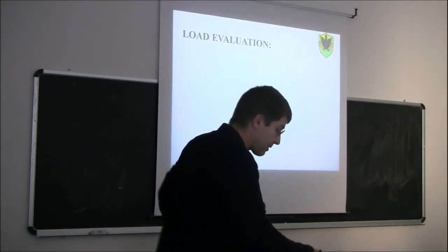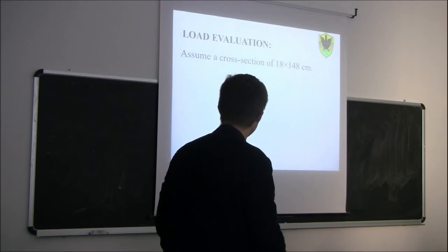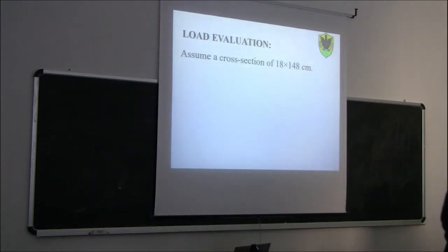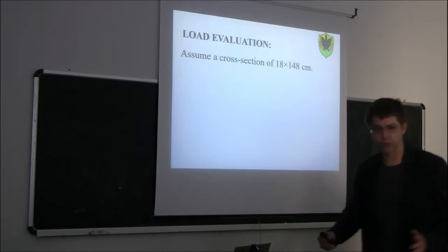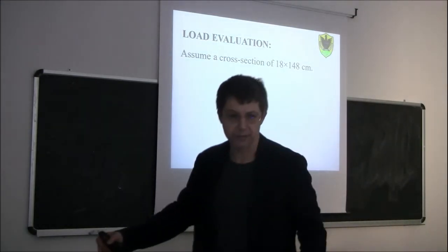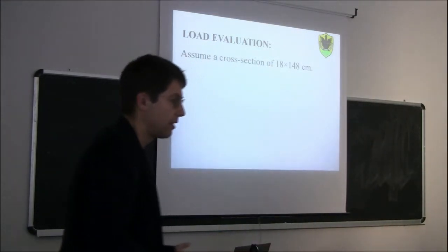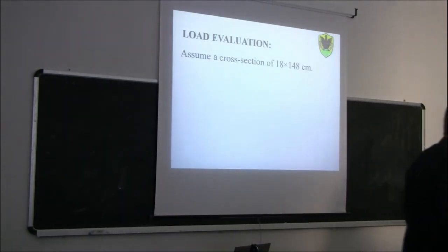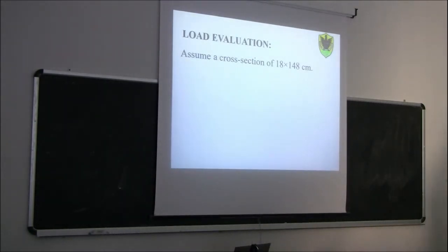Now, if you remember, last time we started by doing a preliminary design of our beam. We said that we have a long beam, about 22 meters, if I remember well. It would be made of glue laminated timber. Of course, when you talk about a 22-meter long structural beam, solid timber is not a possible solution because you can't really find a tree which is that long.